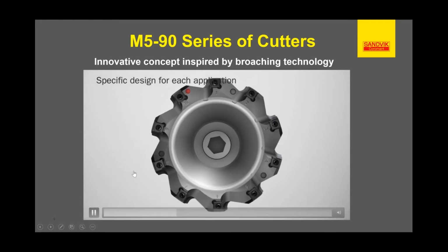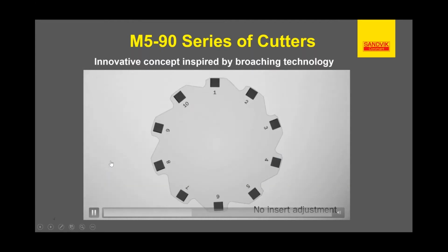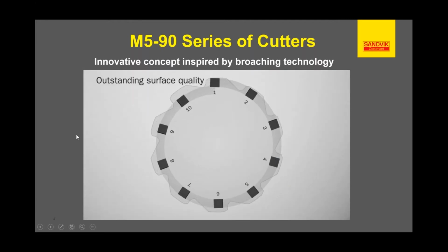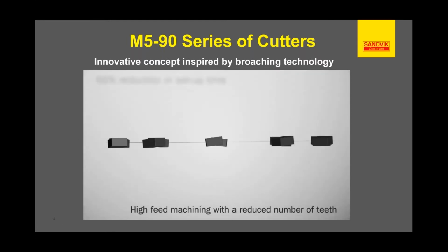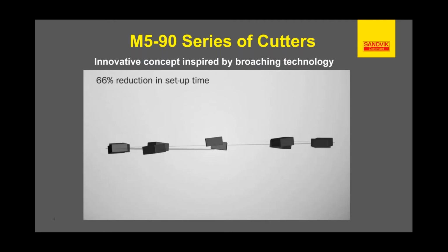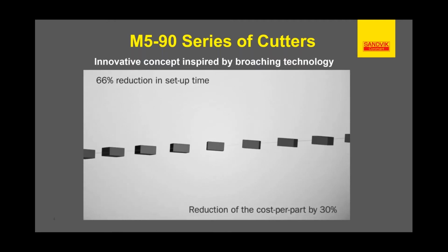So I'll go ahead and let this thing rotate on around. It's going to show you the rotary broaching concept. See, each insert, more depth of cut. Put them all out on a straight line, just like a linear broach would be.